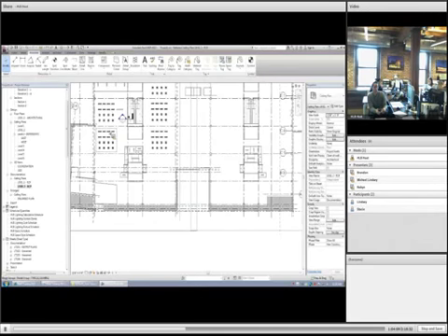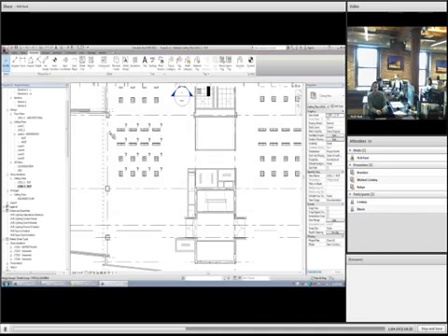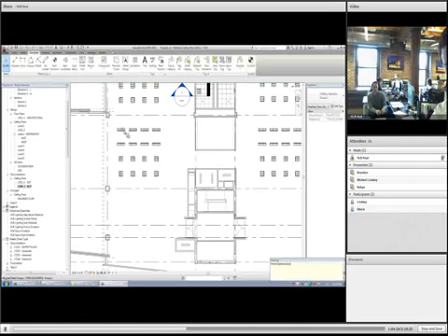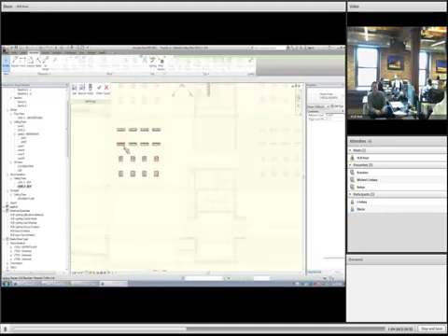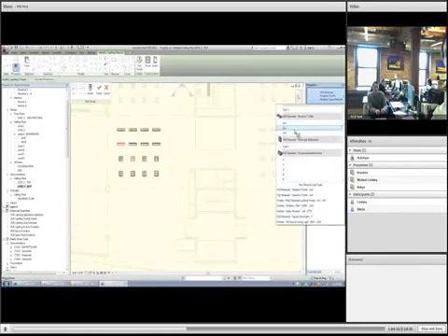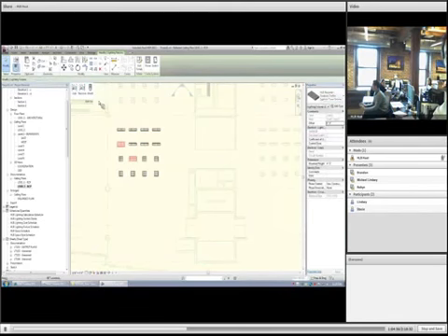But if I, tagging as a group, so if I create a group, and I edit that one group, and then, let's just say I copy that group, will it update the stuff in the other groups? It does. So look at this. If I go into this group, edit group, and I change these two. Basically, every time you made changes to the master room, it updated the other.